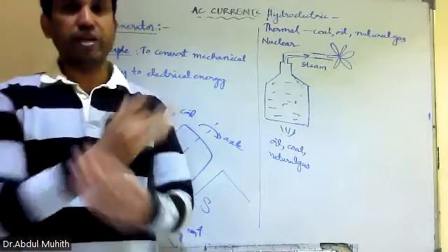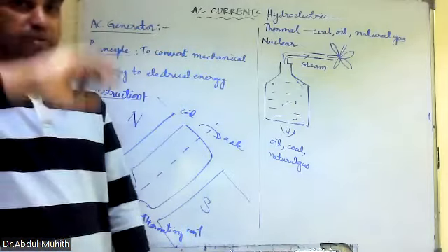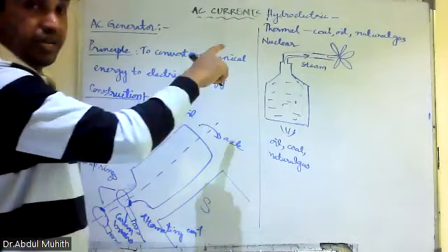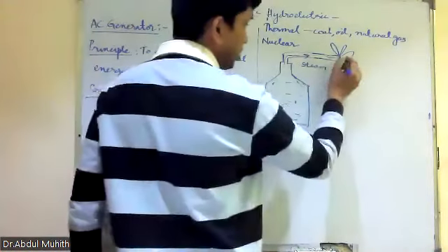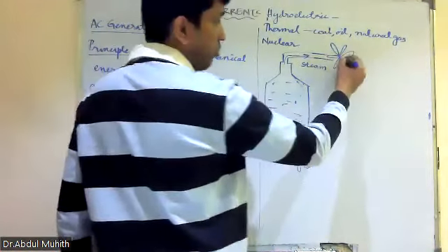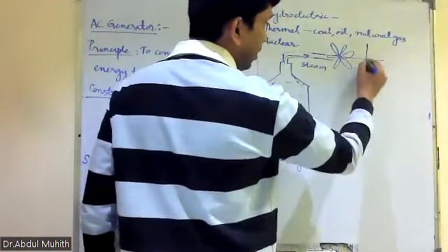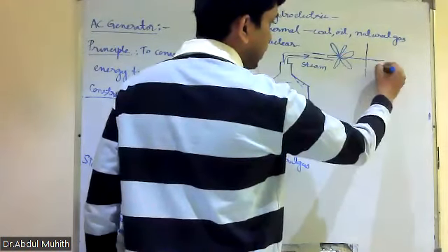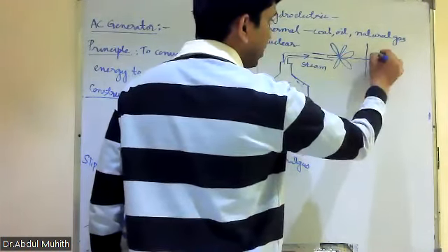Blade on blade, blade on blade. If you see carefully, there are so many blades. So when the high pressurized steam goes and hits the blades, they start rotating. And there is a common axle. This is the axle. The axle starts rotating.